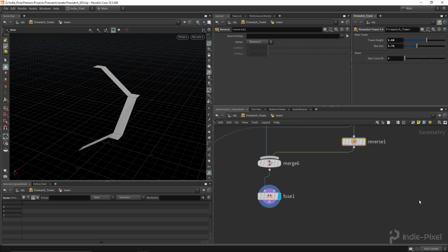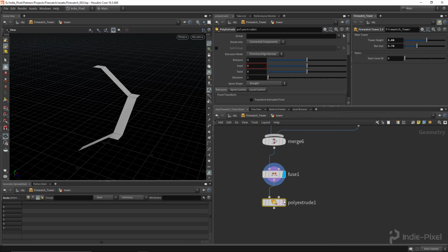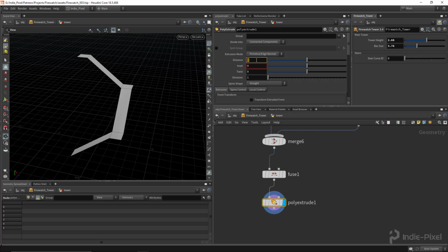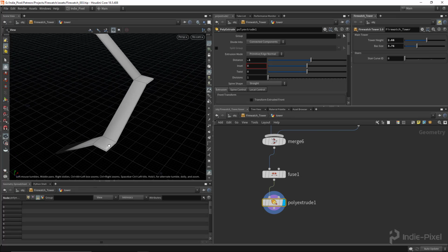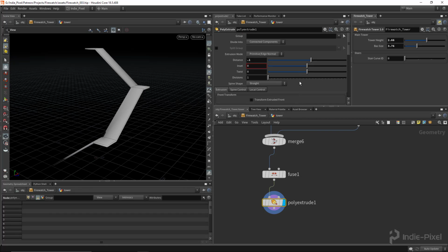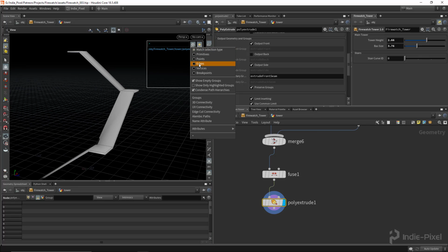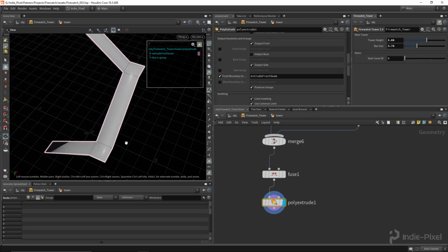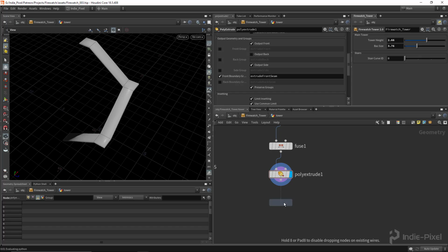Very nice. Alright, so let's do a poly extrude here, and this will actually generate the outside curves for me. So I'm just going to lift this up by something really small, 0.1. That's enough just to give us a little bit of extrusion there. And now I just want to also expose the front boundary group. So this front boundary group's seam is that actual edge group here. So you can see that it actually produces for us kind of the outline of all of our stairs here, which is perfect. So let's go and blast that away.